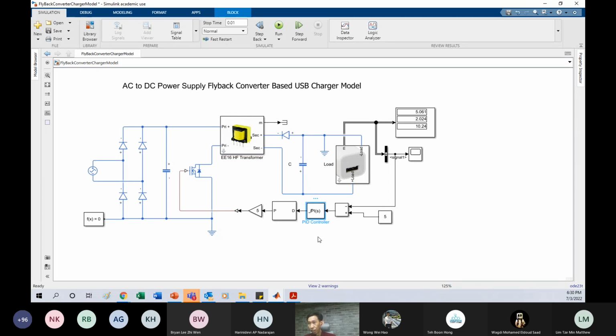Like you see here, it's 325. I reduce it to half of that, and my PI can still handle it and give me the 5 watt output. Okay, so basically this will conclude our DC-DC converter chapter. Maybe I will do a bidirectional if we have time, but I still need to move on to AC already.